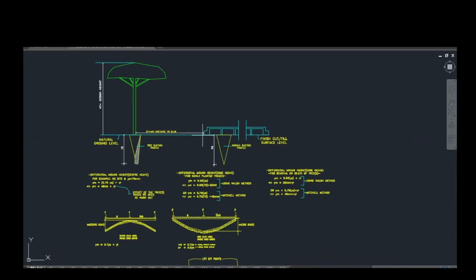While one may argue that this is not really the practical case, especially when we have a single tree on one side of the house, soil drying is just going to be under one side of the house. So realistically speaking, only a portion of the slab will undergo settlement due to the effect of the tree.